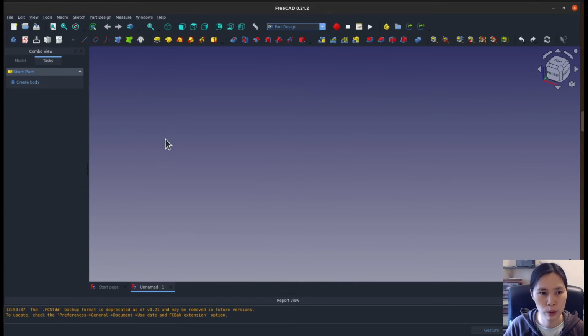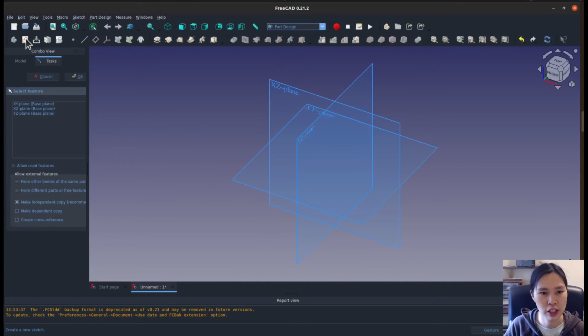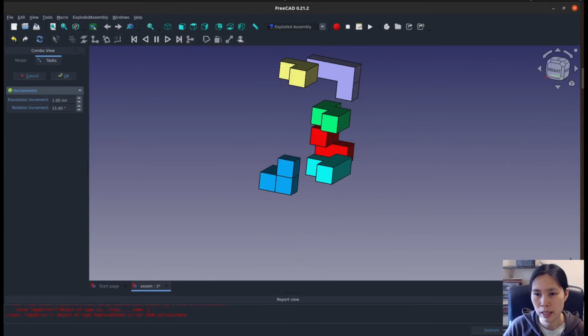So let's go to here. In Part Design, you start with a sketch, and you choose the surface that you want to put it on. Usually you have 2 main surfaces, and the sketch plane that usually goes with it is at the top where you look down, so that you add the height up high like this, or you sketch it on the front and extrude it to the back. Look at our piece here.